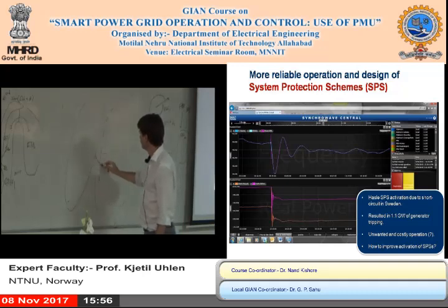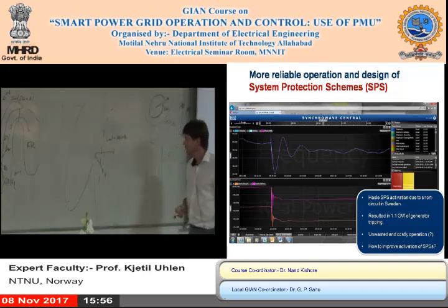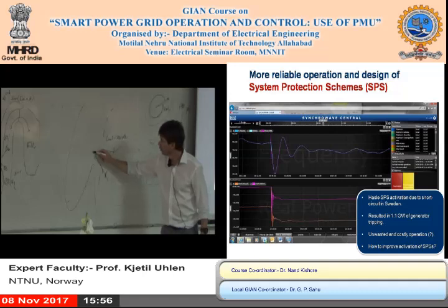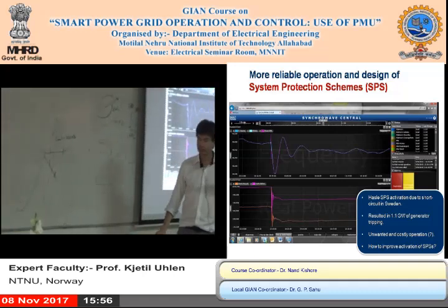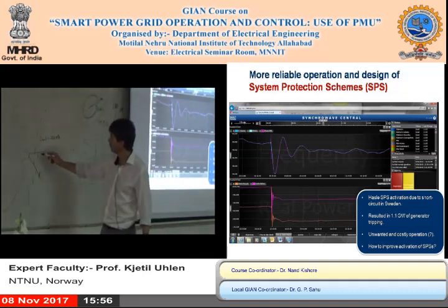Again, we're looking at that corridor here, where you have sort of a limit about 2,000 megawatt. But that is actually above what you could get, sort of, if you want to enforce the N-1 criterion. You could probably only support 1,500 megawatt on this corridor.